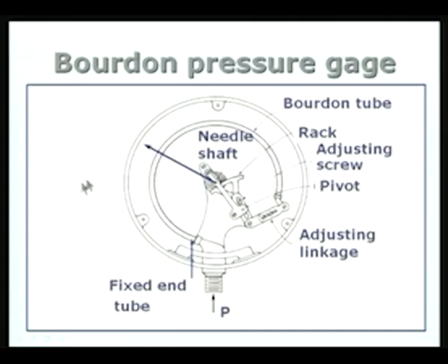The mechanism of working has already been explained. So, with this background, let us look at, for example, the calibration of a pressure gauge of the type which is indicated here. So, what is calibration? Calibration is, in this case, the pointer is going to occupy an angular position, and each angular position corresponds to a certain pressure difference between the inside and the outside, and I would like to make a scale on the circumference of this circle, indicating the position of the pointer, and corresponding to the position of the pointer, a pressure reading must be indicated. So, that is what we call a calibration exercise.